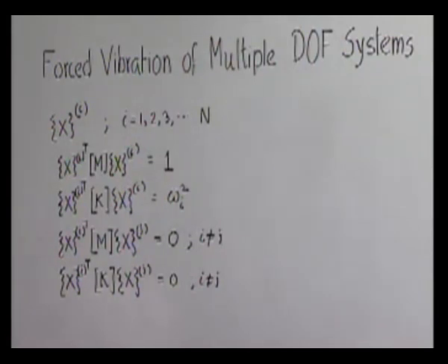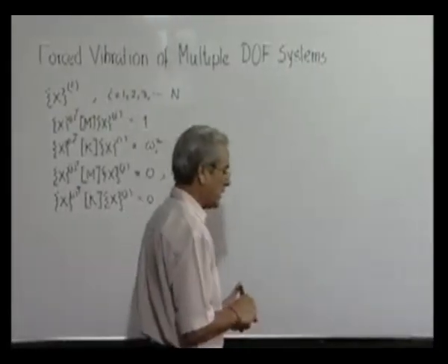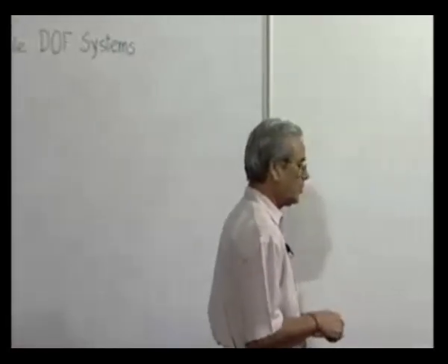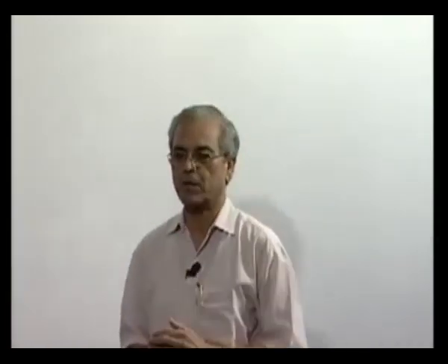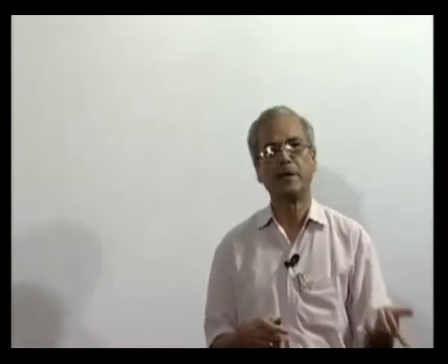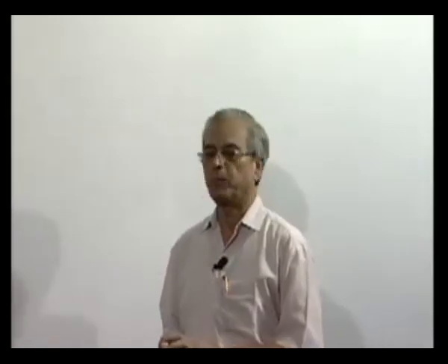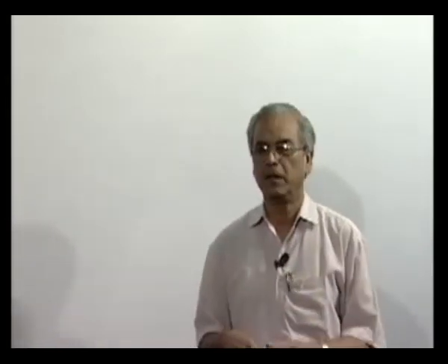Now, as we will see with the approach I will present, it is possible to convert the forced vibration of an n degree freedom system into n single degree freedom systems forced vibration problem. And since single degree freedom systems have been solved and we know the solution, we can use that and then retransform the problem to get the actual desired values.